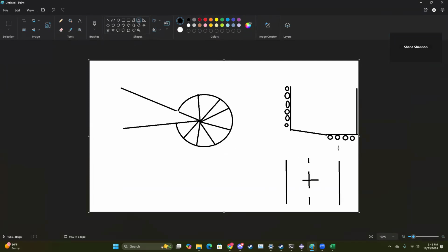In the areas that are not the crack, we essentially put them on rollers. So in this bottom half right here, we put rollers so it cannot move in the Y direction, but can move in the X direction. And if we cut down the middle here, we're cutting down the middle in the Y direction of the part. So we want rollers here where it's locked in the X direction, but can still move in the Y.